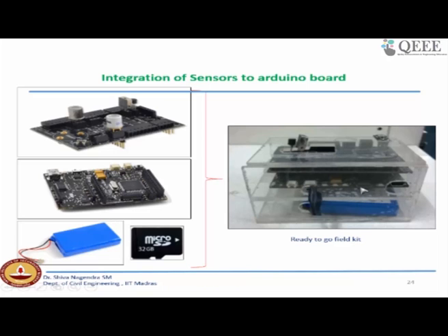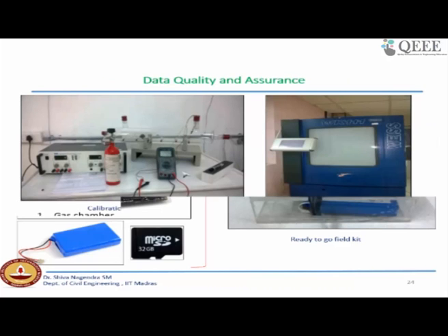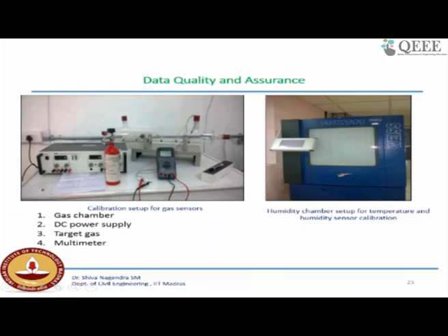The particulate matter concentrations even give some different bins, ranging from 0.3 micron up to 10 micron. There are some issues associated with these sensors. Since they are low cost sensors, we need to calibrate them. There are 2 types of low cost sensors. You can use semiconductor based low cost sensors or electrochemical based low cost sensors, so you can use them for air quality measurements.